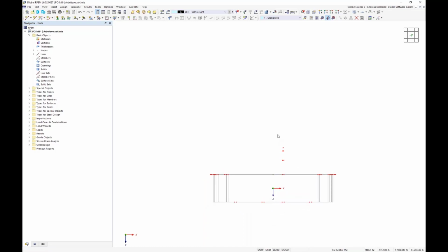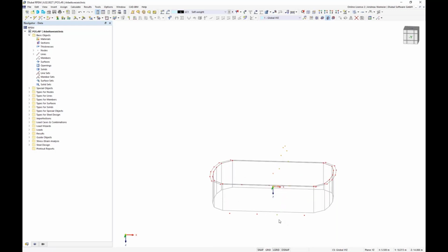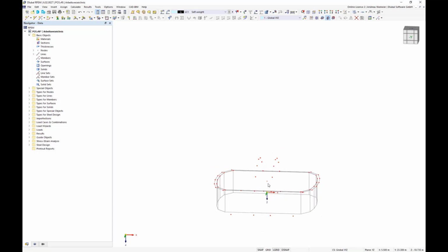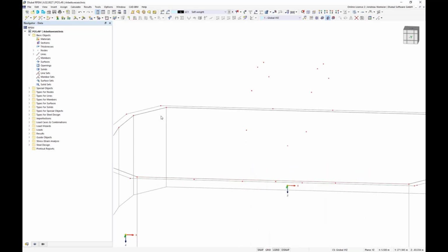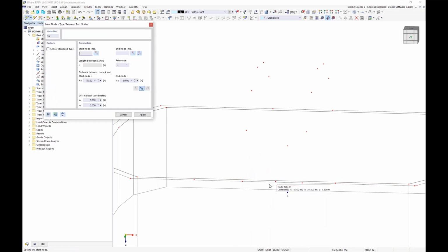Then we have now some nodes which we can use for spline definition. Because we need these control nodes for the other arc also, I copy directly this basis on the other side and create directly here this geometry with this lifted arc. For this, I need a center in between. I use this command node between 2 other elements here, apply.